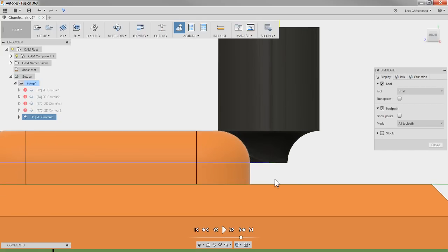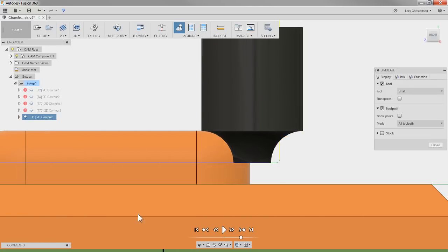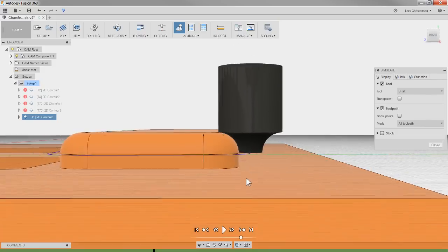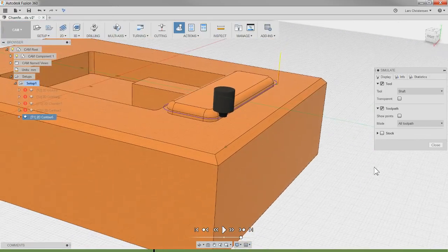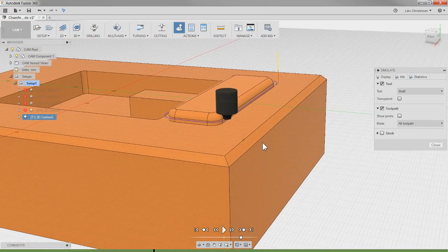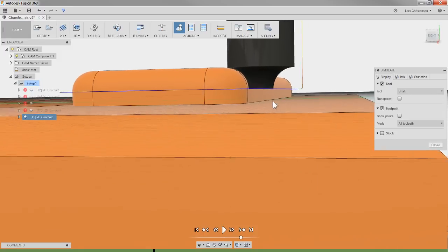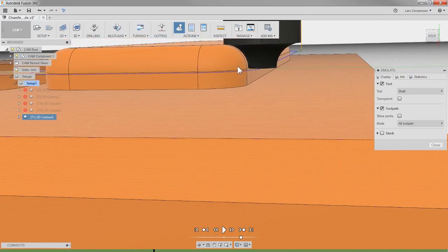So now you can see here how the radius cutter is going to come around the corner there. So it comes down and makes that beautiful, beautiful radius right there. Of course, this is kind of like the golden way if you have a radius cutter on here. So just remember, you will touch off the bottom of it, and then you are driving the bottom of the radius.